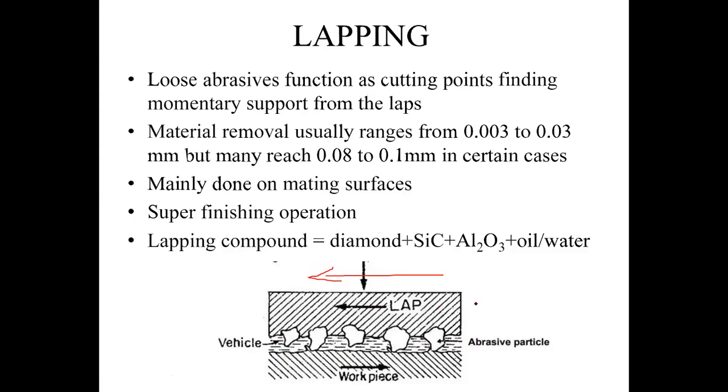We move this lapping tool under some force. When you apply force and move it, because of friction and pressure, the abrasive particles also move along with the tool. Since they already have sharp edges, these sharp edges contact the workpiece and move forward under this force.